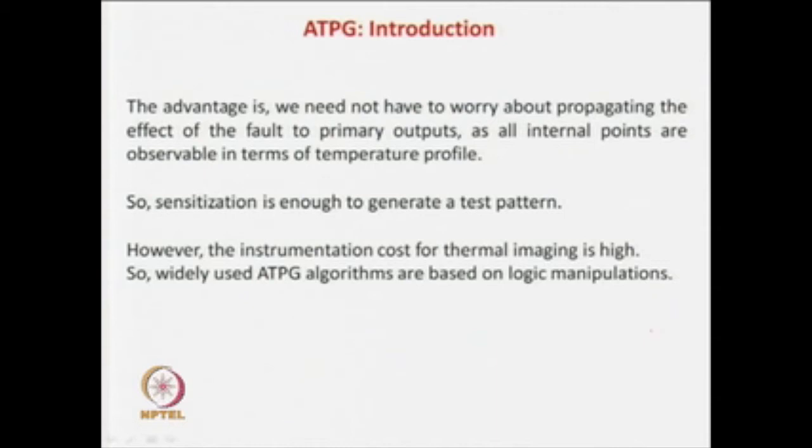With thermal imaging, you have to take the image, go for image processing, and find out which is the hot spot. That takes more time for testing, and the equipment is very expensive. So, again there is a trade-off between logical testing and thermal imaging based testing. Sometimes we go for thermal imaging and sometimes for logic manipulation. But generally speaking, in the first few rounds of silicon fabrication, there may be a lot of defects based on manufacturing and design problems.